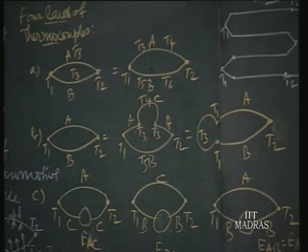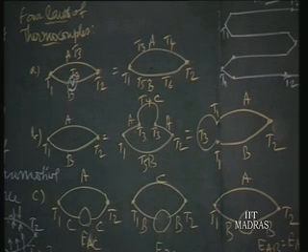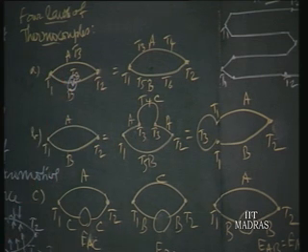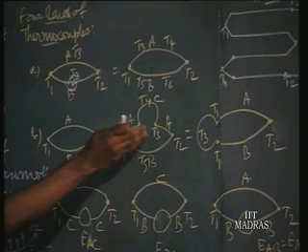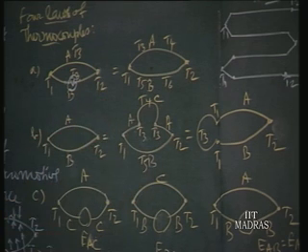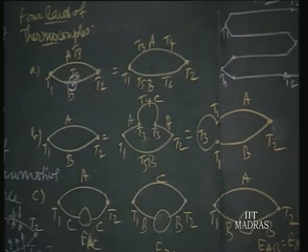This is the property what is made use of in the voltage measurement of the thermocouple circuit. When you want to measure thermocouple circuit, what you are doing? We insert a voltmeter. Voltmeter mostly consists of copper wire, and we find the 2 junctions we are making is at the temperature of the atmospheric condition. Atmospheric temperature is the new junction temperatures, so same temperature. So this condition is satisfied. Hence you find the voltage developed, thermal EMF developed in such circuits is no way affected in the earlier circuit where there is no such voltmeter.